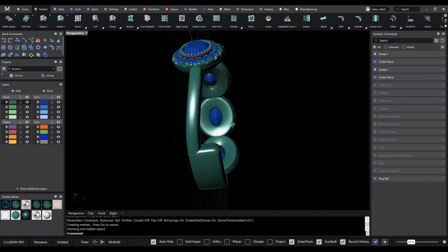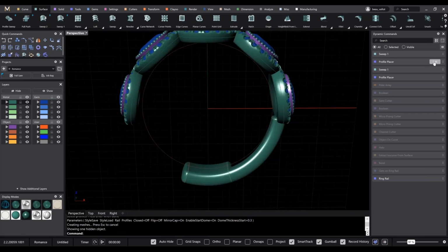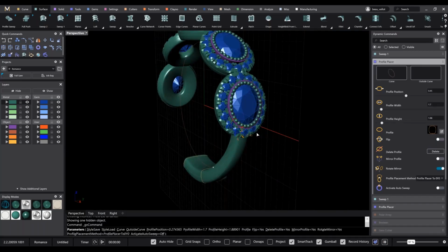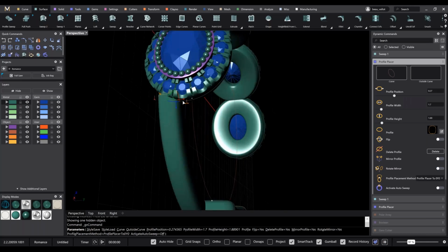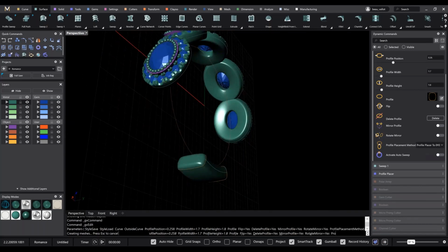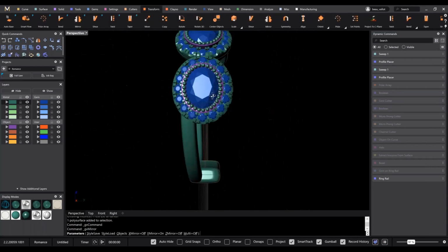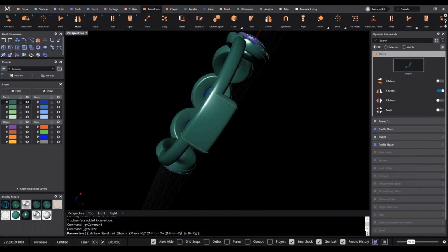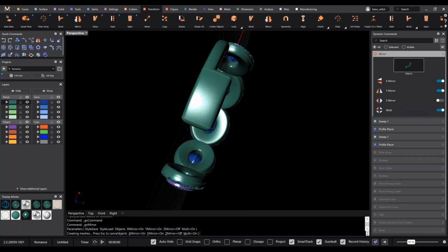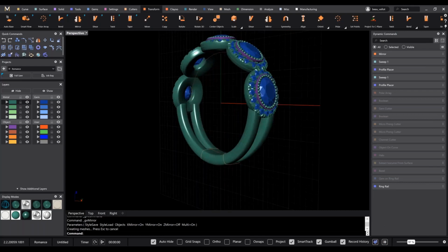and we can bring this one back. So I did this kind of on purpose. So right now it's in the middle, right? So we need to edit, select this profile, and we can just drag it out to where we want it. We can reduce the height and even pull it up like that. Now we just mirror. So selecting the object, transform, mirror, except I want to go 4 directions. So I toggle X and Y, and then the multiple at the bottom, and right click. And there we go. I would probably open this up a bit more, but we're out of time.